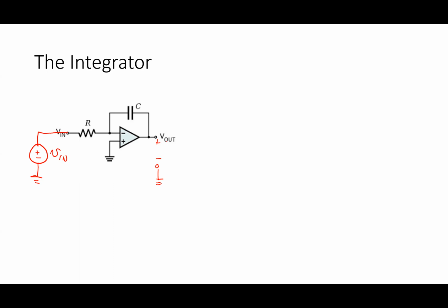Well, I can still do nodal analysis like I did before. So I've got V1, this is V2, this is I2, this is I1, I have I plus, and I minus right there. Where do I start with any of this analysis? Golden rules, right? I write those down for myself: I plus equals I minus equals 0.